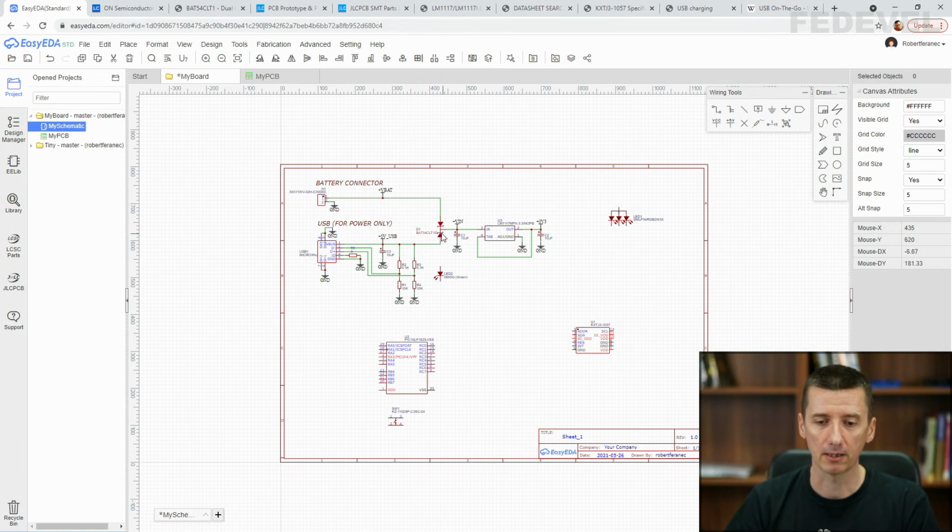But for this power LED, when I calculated this minimum value of the resistor, the LED was super bright. It was disturbing. It means I had to actually try different resistor values. I just desoldered one resistor and placed a different one.